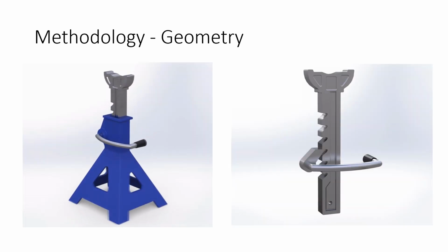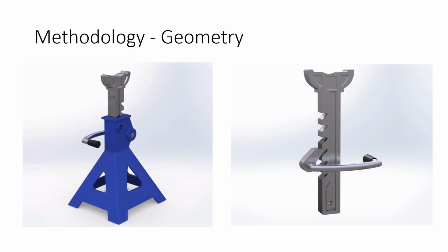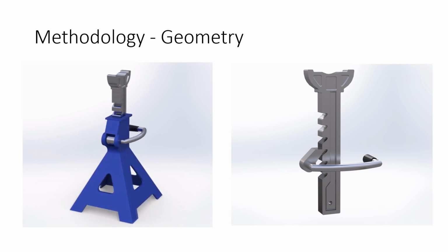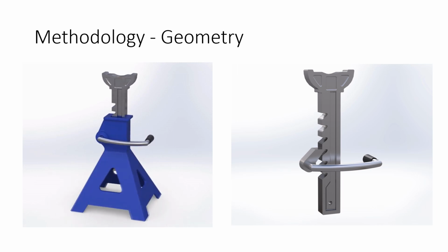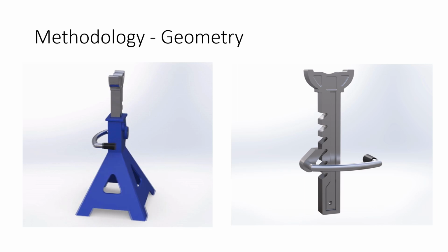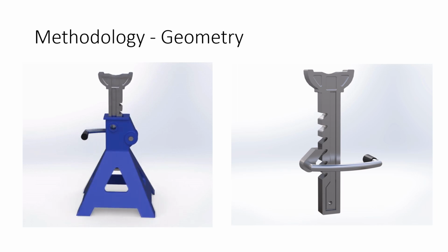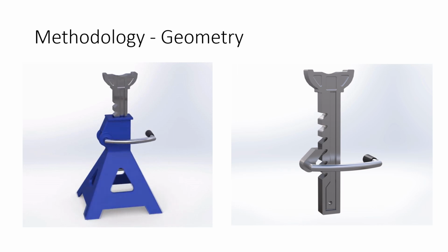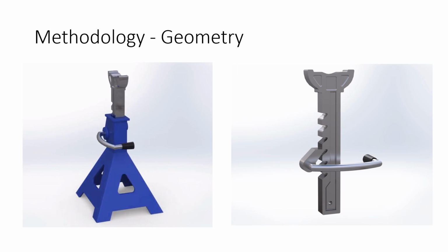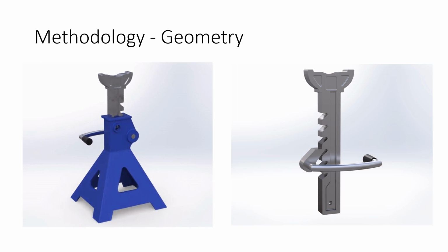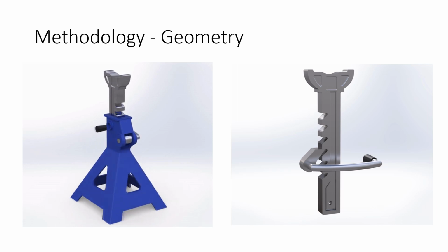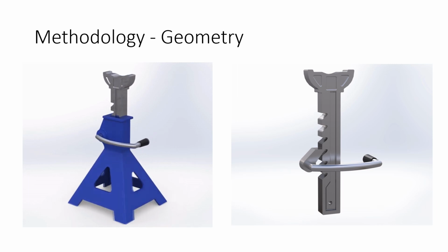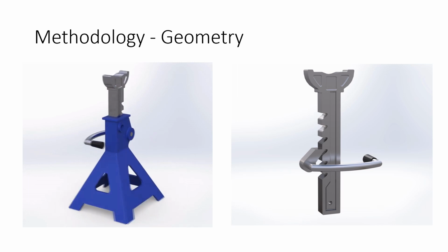The geometry was created by using SOLIDWORKS and physically measuring a Harbor Freight brand aluminum jackstand. Each of the three main components, the jackstand frame, the ratchet bar, and the adjustment arm, were modeled separately. Simplifications were made to the adjustment arm geometry due to the fact that it was pinned inside the jackstand, making it difficult to access for measurement. An adjustment height for analysis was selected, and then the parts were configured to a SOLIDWORKS assembly, where contact between the faces of the components were defined.